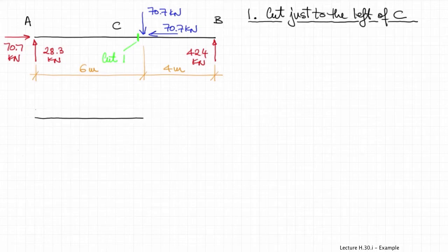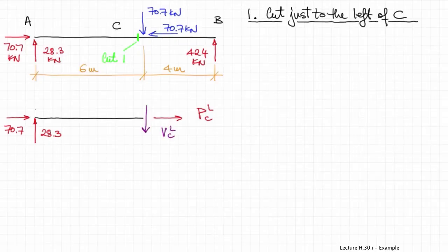So we only have to draw that one, like so. The internal forces I will always draw with their positive direction: shear force going downwards on the left-hand side of the free body diagram, bending moment rotating counterclockwise, axial force pulling out from the beam.